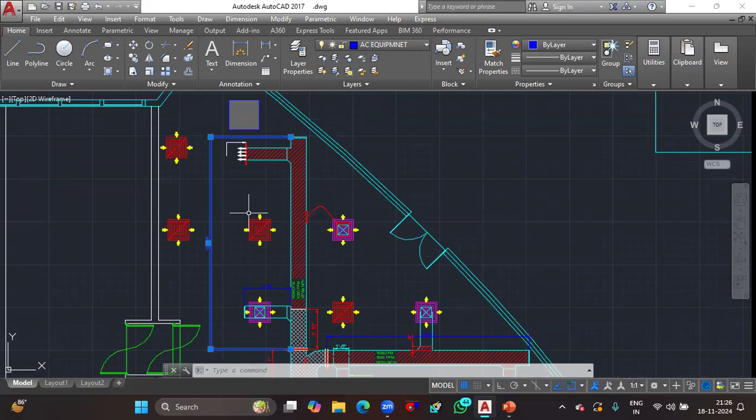So initially in the duct classes, I explained that circular ducts have lesser head losses or pressure drops than rectangular ducts. Why? Because rectangular ducts have more surface area compared to a circular duct. So it will induce more surface area, which creates more friction right inside the ductwork. It's not risky, what I'm saying is it will create more friction drop, pressure drop inside the ductwork itself. So in order to account for that, we need to find out the exact HP of fan motor that will be required for the project.